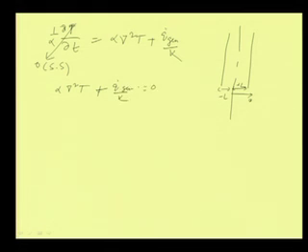But as we said, it is only in the x direction, so this alpha won't be there. We can write d square T by dx square plus q dot gen by k equals 0.